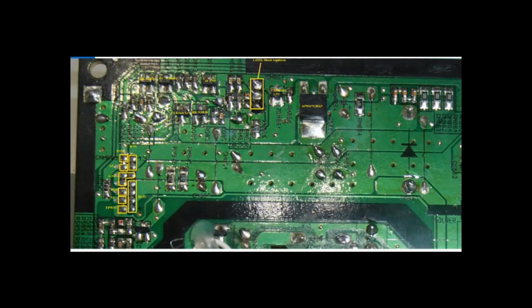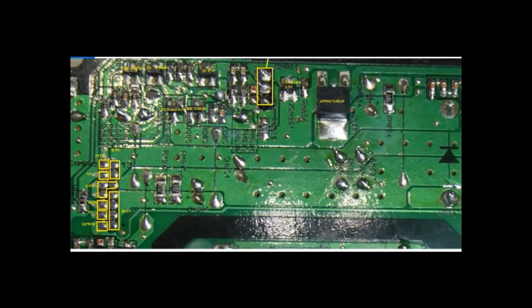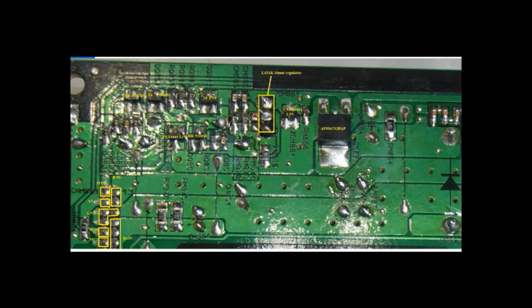Now we need to make sure what the other components involved in this board are. Actually, this is a little difficult to troubleshoot, because there are SMDs, surface mounted devices, all around. But if you carefully look through each element, you can get some sense of how this works. There's an N channel MOSFET here and two diodes coupled together here. It is marked A4. This is the standard way of marking the